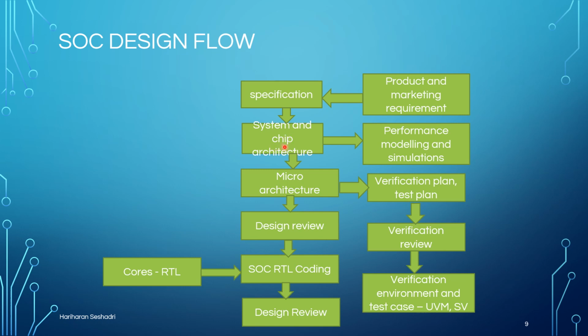So we'll look from the hardware point of view now. From the hardware spec, we write something called a microarchitecture. So what are the various blocks? We saw in the previous slides, there is CPU, there are peripherals, and we saw a bus interface, and IOs, JTAG, and all this, right? So that's a microarchitecture block level diagram we prepare, right? So from the microarchitecture, that's a basic reference, we do a verification and test plan.